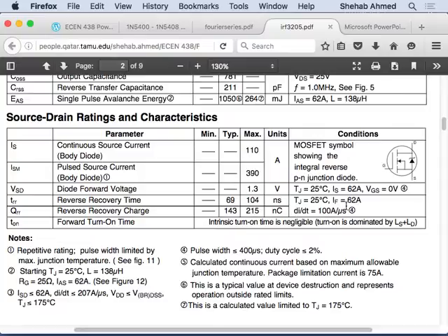Yeah, so it will, for a certain value of current, obviously. Because charges, they give you the charge, right? If you have a high voltage that will be pushing in a high current, then you will be able to push this charge quicker. But it still has this reverse recovery time, which has typical values and maximum. They will give you, so typical value is about 70 nanoseconds to 100 nanoseconds. So if it's a higher current that's doing it, maybe you'll do 100 nanoseconds. It's in this range, right?